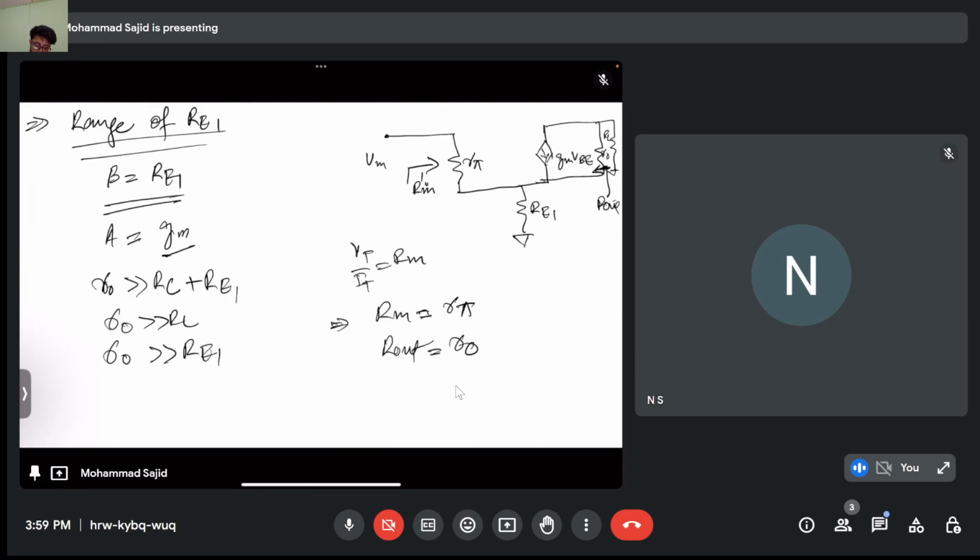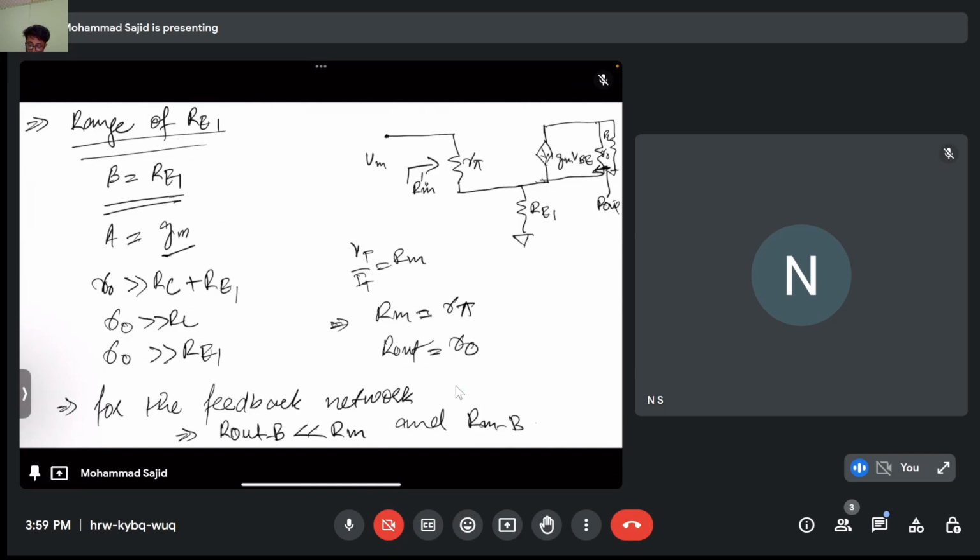Now for the feedback network, what are the conditions? You have gone through the videos, right? So your R out of beta, that is the feedback, should be less than or equal to Rin, and your Rin for the feedback network should be less than R out.